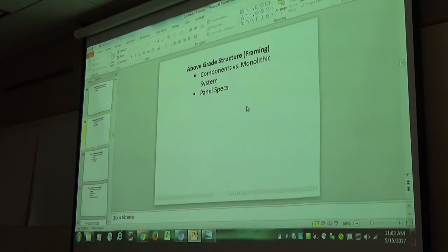The inch and an eighth flooring is rated for a 4-foot span. Sure. Yeah, I mean, the characteristics that they publish for structure are for use in a horizontal orientation, where you're loading it out of plane. It's nothing that you stack up and put an axial load on and push that way. There's nothing published there. So we have to extrapolate from one orientation to the other. Right. But it's pretty clear. I mean, in some ways, this thing is twice as strong as a competing OSB that's inch and an eighth.